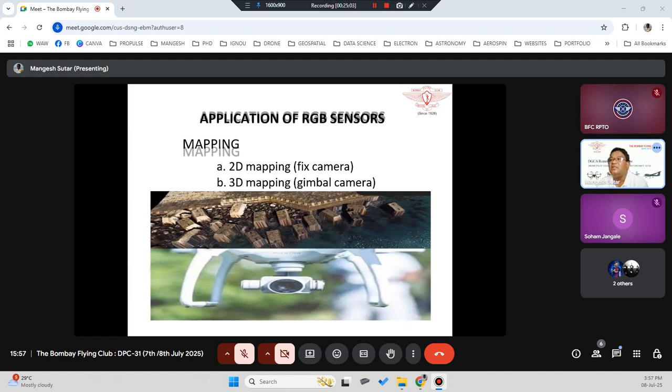So how are they taken? They are taken by using a gimbal camera. So you are actually changing the angle of your camera at different positions, and you are capturing the footage. So that means you are getting the images at different angles. Okay, and then you stitch them using a software. Normally this is not done manually. There is a software which checks all this data, and the images are geotagged and all the things, and then these images are being created.